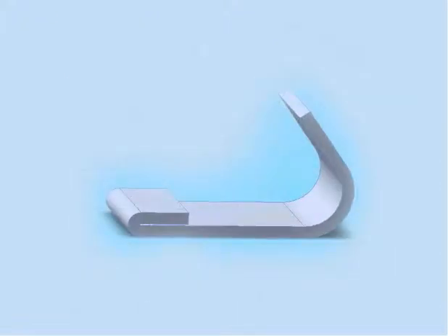One last point I wanted to bring up here. Let's take a look at my model. Different degrees of bends have different K-factors. The wiped hem on this part has a K-factor of something like 0.3. On the other hand, a softer or gradual bend, as you see on the other side, has a higher K-factor of about 0.5. And this concludes our tutorial on some of the theory behind sheet metal bending.